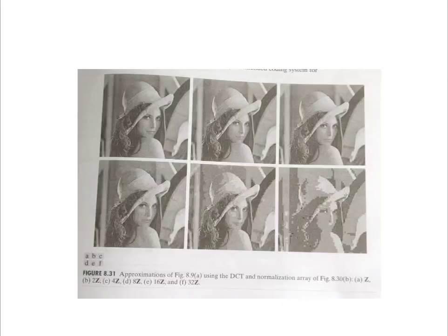The image is first subdivided into pixel blocks of size 8x8, which are processed left to right, top to bottom. As each 8x8 block or sub-image is encountered, its 64 pixels are level shifted by subtracting the quantity 2^(k-1). The 2D discrete cosine transform of the block is then computed, quantized, and reordered using the zigzag pattern to form a 1D sequence of quantized coefficients.